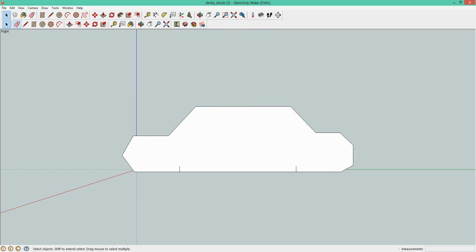Okay, once you have both of your lines drawn, it tells you to go ahead and use the circle tool, and it tells you to go ahead and click right in the center where you just drew that. Click it, and again, notice where it says down there in the corner is going to say radius, and it says it wants a radius of at least 12. Okay, so I'm going to go up to at least 12. Alright, so there we go, 12.0. So notice again, it says down here radius 12.0. You can do the exact same thing to the opposite side.